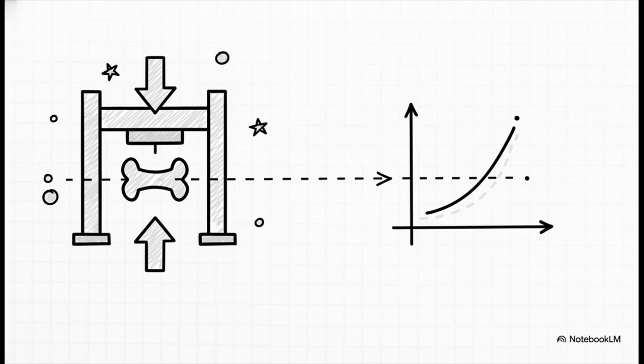You know, the process is pretty straightforward. Engineers take a little piece of a material, they stick it in a machine that just pulls on it, and they measure exactly how much stress is building up and how much strain is happening. The graph they get from that reveals everything: its strength, its stiffness, its whole personality.